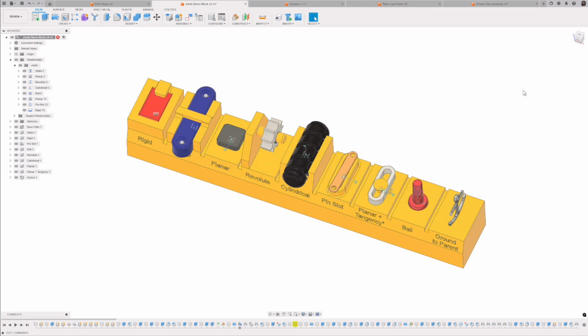If I just go OK now, we have a slider, for example, which allows it to move along 1 degree of freedom. We have planar, which allows translation in 2 directions and also rotation about another one. So we can also rotate around the one that's locked. When you really speak to people, that's where a lot of the confusion comes, in that planar joint.